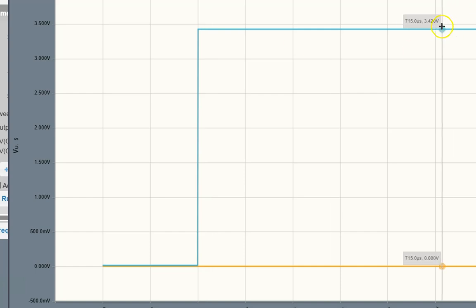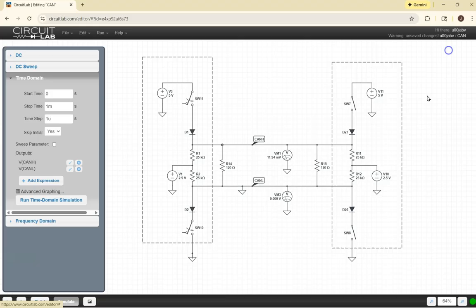So this is the same kind of thing that you're seeing. I see a difference in my failure depending on which, CAN high or CAN low, gets shorted. So as we saw, if I short CAN low to ground with this passively terminated network, there's a good chance the network's still going to function. I might not even know that I have that short to ground, other than maybe some intermittent problems. It's definitely not something we recommend, because it's a terrible signal to noise ratio, meaning it's not very robust, but it's a failure that's tough to detect otherwise.